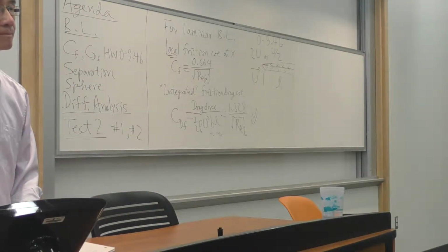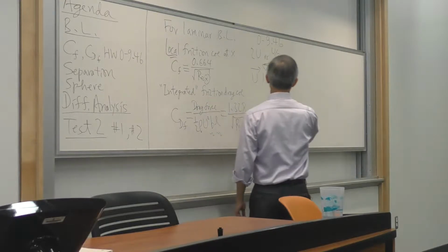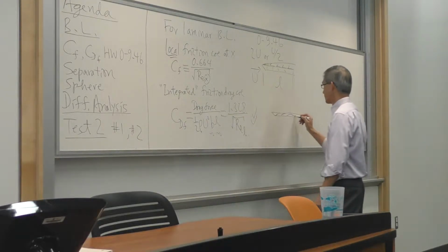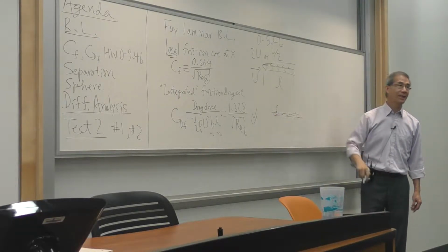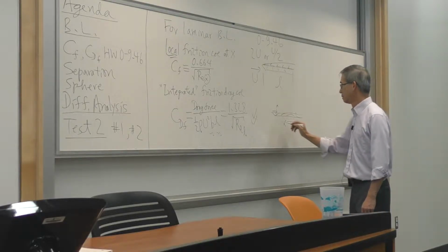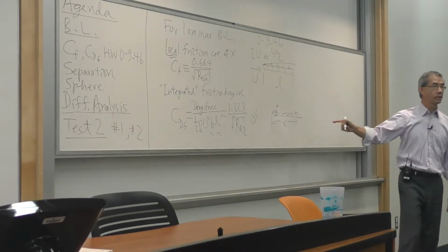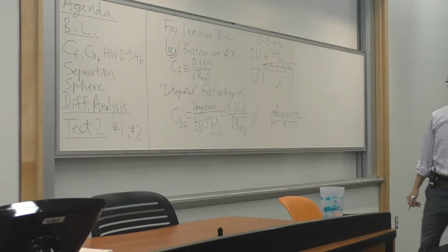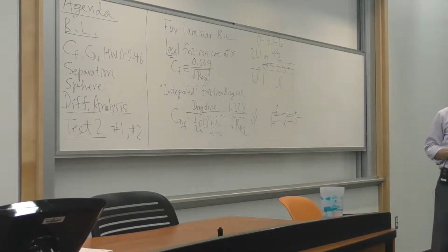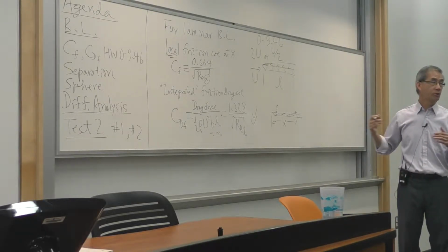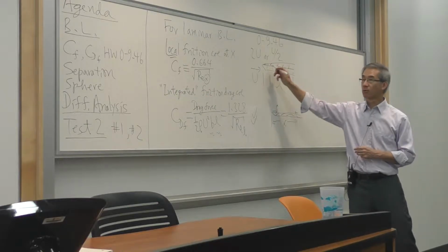Yes? That just means it changes as we go down the... Absolutely. So the local meaning at a point. Not using the same diagram, but the local meaning is at a specific point at distance x from the leading edge, at that very point, and that single point only. What is the drag coefficient, locally at that very point? Whereas the second equation is an average integrated overall frictional force due to each of those small pieces.